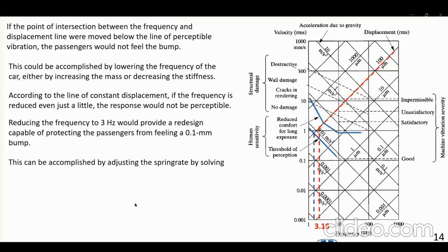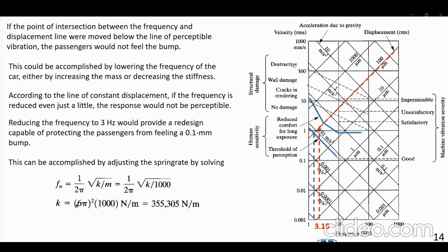So how can we do this? Well, remember that the frequency is given by this expression, okay? Now, if the mass is fixed, and we can change the suspension stiffness, and if we want this thing to be 3, as we want it here, this is intended to be 3, that purple one, then you work it out, you get k equal to this.